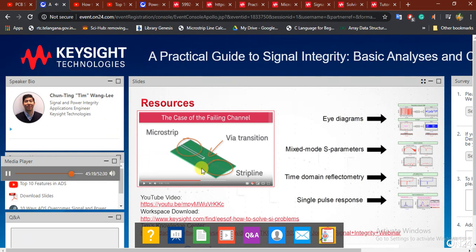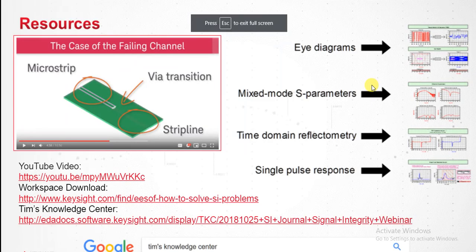Yes, ADS does have a Libra model, but I do suggest you use the control impedance line designer. Not because I'm selling you the tool, but because the Libra model uses an equation-based solver, meaning that it plugs in the numbers and gives you the result, which does not include conductor loss that precisely. So you do want to use the control impedance line designer because it's doing a 2D cross-section using method of moments and solving the Green's function, and that's more accurate. Thank you, Marco.